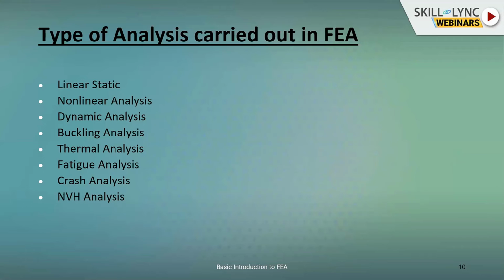So it is a very simple analysis, very easy for the software to solve. Here we can also apply the superposition method, and the results are scalable. So this is basically linear static analysis, but it is only valid where you have constant material properties, no complex contacts, and no nonlinearity present.